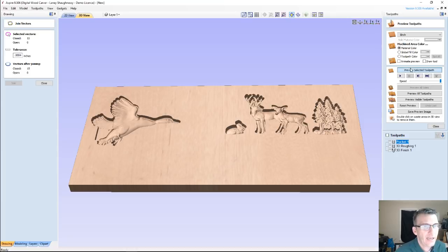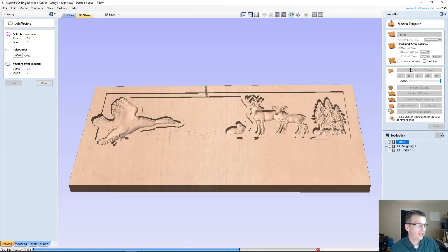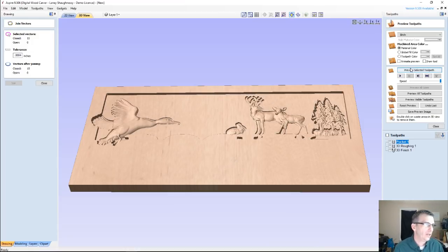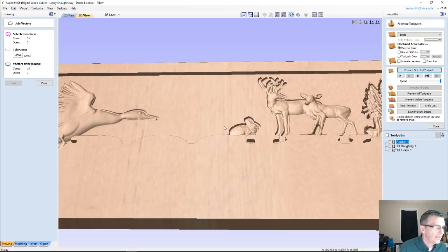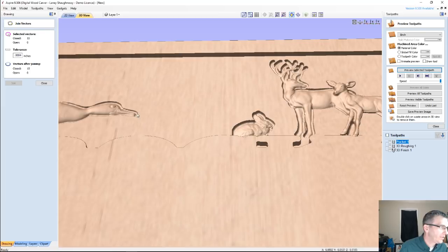Alright, now I should have the proper depth for my pocket. My models shouldn't be screwed up. Had a little bit of an overlapping line. I'm still a little off on my depth. Let's see what I need to get down to. I'm sitting at 0.5063, 0.51. Remember, I'm working down from 3/4, so the top of my board is 3/4, not 0. So I'm working backwards.